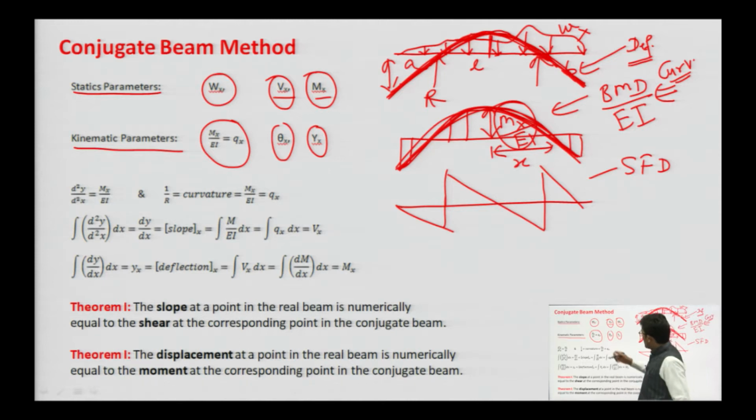Now, if we replace the bending moment with the curvature, meaning bending moment divided by EI, and the loading is replaced by this, then theta x, the slope, is directly interlinked with shear force.